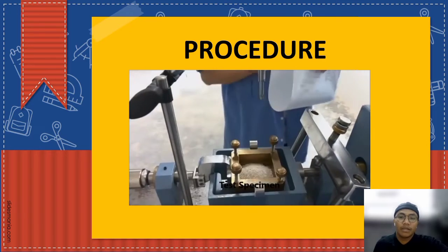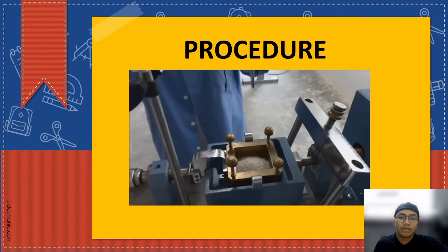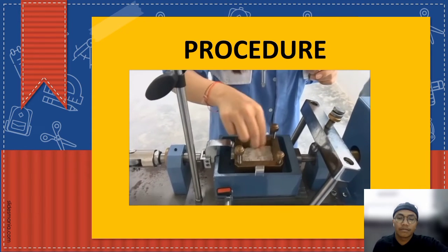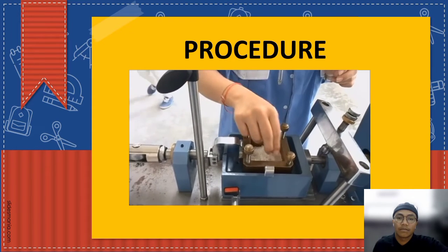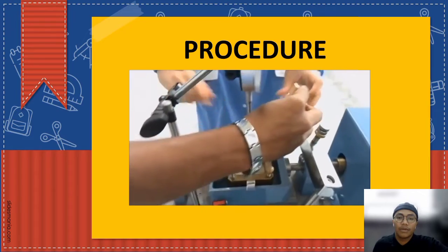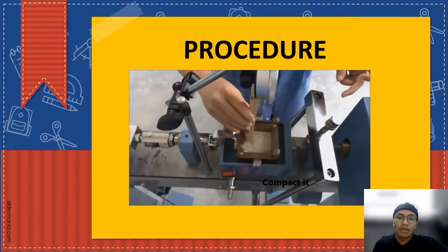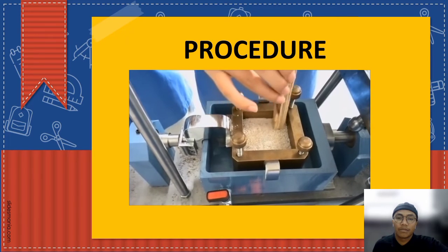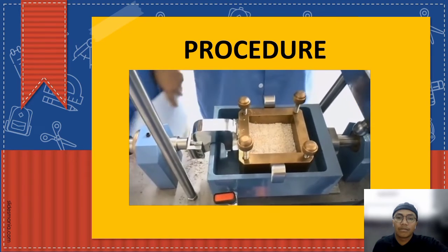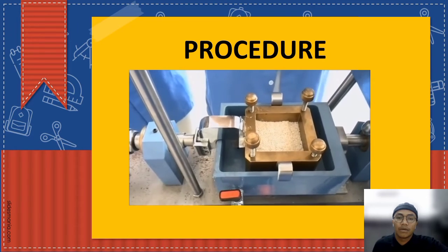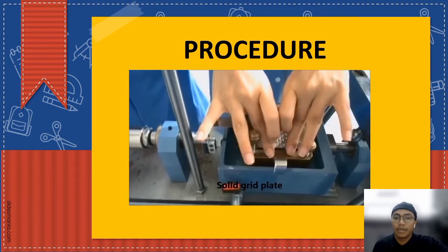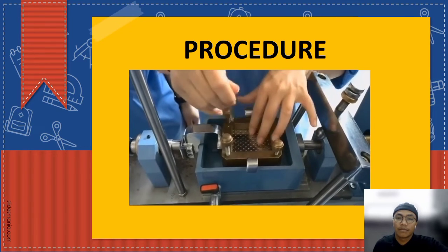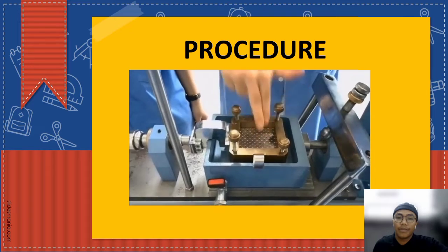Also, compact the specimen. Then put the solid grip plate and place it properly. Then put the porous plate, and also the loading plate.